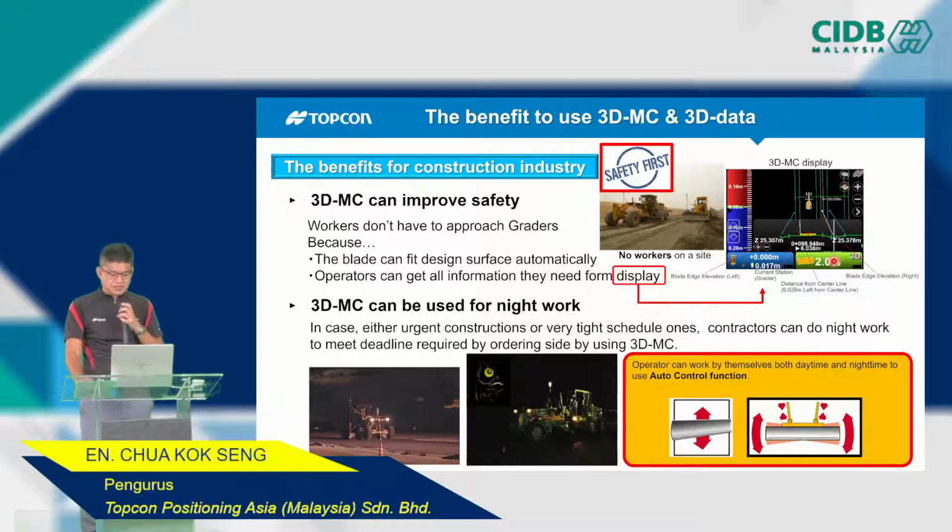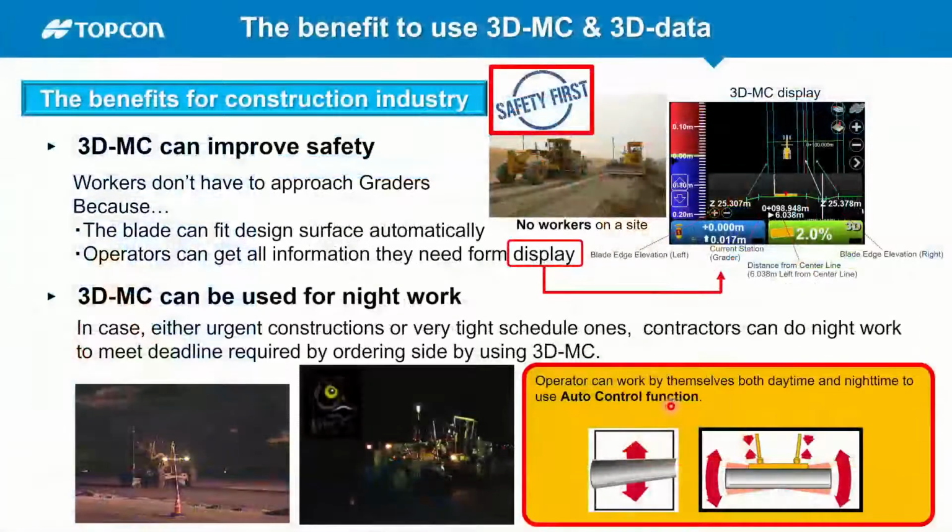Okay, so to add on, 3D MC can be used for night work as well, because it has an auto control function. Once the design data has been sent to the operator side, which is the iPad, I mean the mini screen which appears at the operator side, they can just view it and do all the auto control using the required cut and fill, okay?